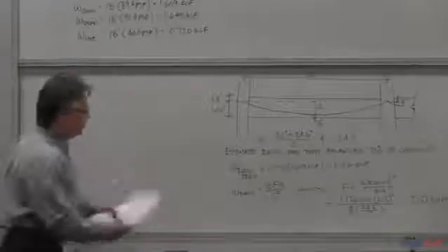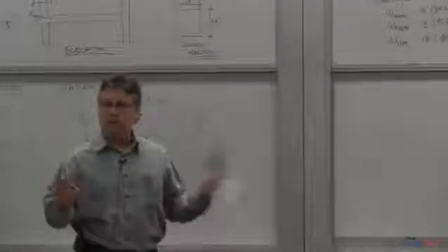Okay, this wasn't the only thing that I stated that I wanted done. I also want 250 psi. Most offices require a minimum of 250 psi on the cross-section. The cross-sectional area is 940 square inches in this section.